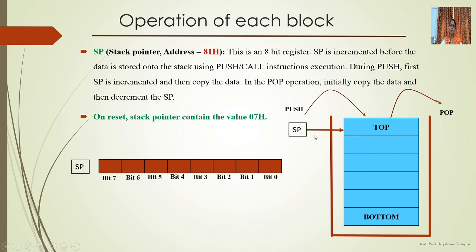So if we want to store data onto the stack, then first the stack pointer is incremented and the data is stored into the stack. If we want to retrieve data from the stack, then first the data is taken out and then the stack pointer is decremented by 1. So upon reset, the value of the stack pointer is 07H.